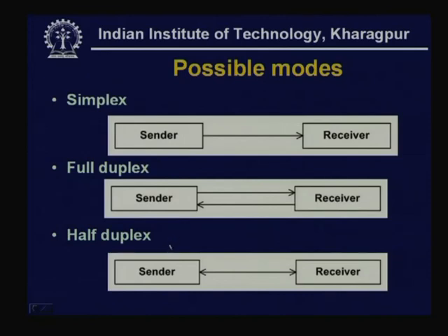In half duplex communication, as you can see, you have got only one channel, but communication is taking place in both directions. Obviously, the communication cannot take place in both directions simultaneously. In such case, we have to use some protocol. For example, when a policeman is talking to his headquarter, he is talking, then he says over, then listens for some time, then he again starts talking. So, they have a single communication channel through which the headquarter is communicating with that policeman.